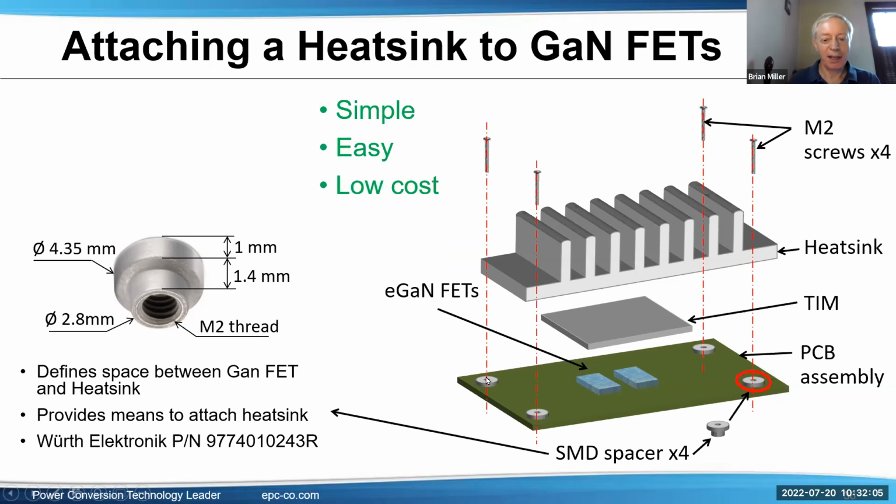Well, a nice little easy way to do it is to put some spacers in. These are actually threaded hole surface mount spacers. They can be put in. As it shows here, it's about 1 millimeter spacing from the board to the top here. A TIM, a thermal interface material, which would go on top of the FETs to conduct heat through the gap between the top of the FET and the heat sink. And the heat sink over top with some screws to screw it down. This has the advantage of a good thermal contact without having mechanical stress going right from the heat sink onto the FETs.